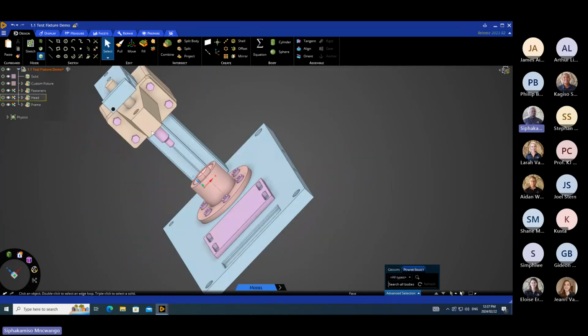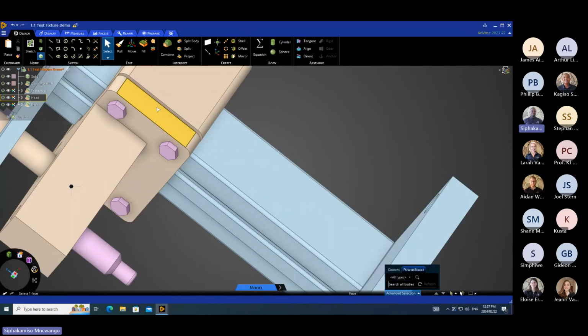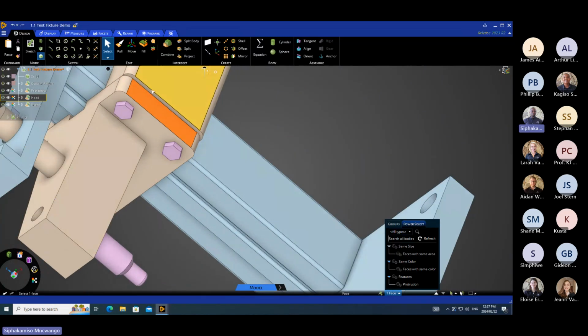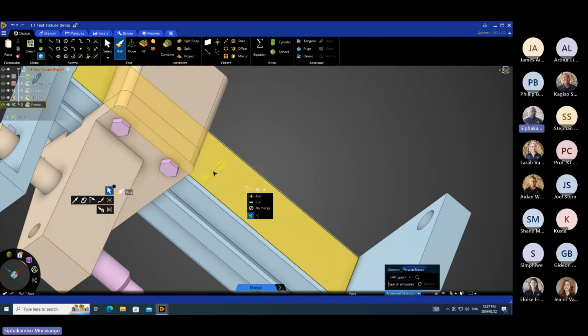And then the other geometry prep tool we haven't talked about yet is pull. So if we have misaligned edges like this, we can press P, or go to Design and choose pull, or use our hex. And then we can use our up to and pull it up there to just align that.